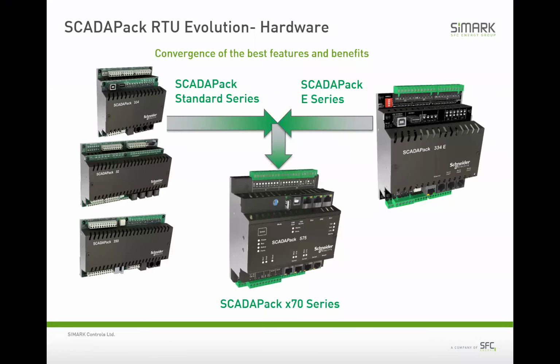For many years now, we've had the E-series generation of RTUs focused on the DNP protocol and the standard series, which are more focused on the Modbus protocol. Both of these can be configured using our Workbench software, which gives you IEC 61131 programming language access. The standard SCADAPack also can be programmed using our ladder software, the Telepace Studio. So when designing a new generation of SCADAPacks, we've taken a lot of the features of both of these devices, and Schneider has combined them into one new range.